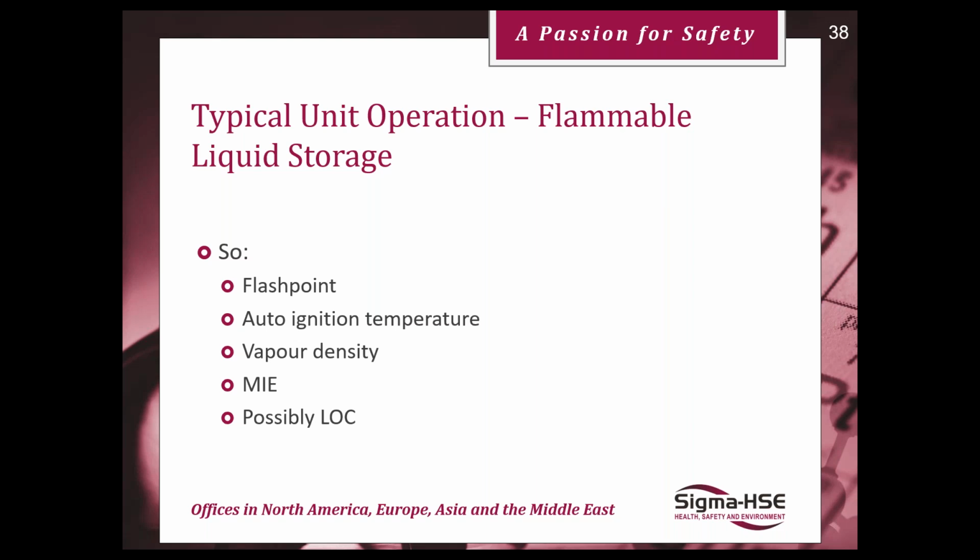Therefore, we need to make sure our earthing is very good and take precautions to prevent charge build-up on liquids. So you'll see things like trying to avoid splash filling, because creating aerosols and mists will generate a lot of charge. Impacts onto the side of tank walls can also create charge, all of which you've got to get rid of effectively, otherwise you could potentially have a static discharge.